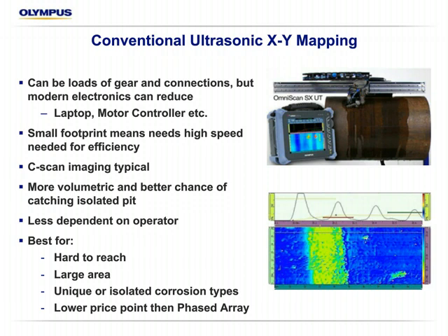As long as we have a good system that holds the transducer properly to the surface and our coupling delivery system, we're really taking a little bit of the human element out of it. Because it's more volumetric and we're going to scan the entire area, you really do have a better chance of detecting isolated pits. Again, if you are taking a sampling with a thickness gauge, you're only measuring the number of points that you measure. So right next to it, there could be a pit, especially with microbiologically induced corrosion or these through-wall pits that can occur without presence of general wall thinning. This is going to have a much better chance of getting an indication that there's something going on besides a larger area of general wall thinning.